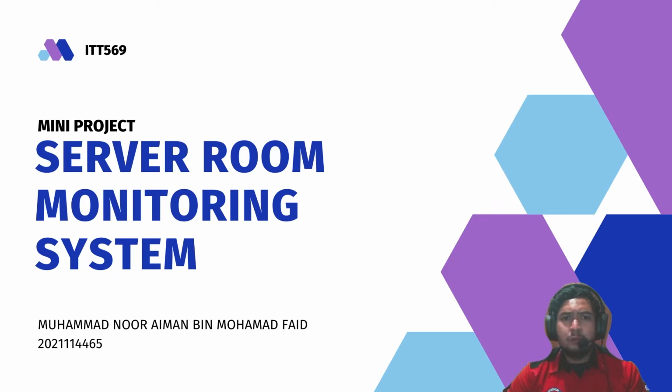For now, I will present my IoT mini project, which is a server room monitoring system. This system will record and send the temperature, humidity, flammable gas, and fire detection to the Blynk server so that it can be displayed on the Blynk mobile application. This monitoring system will also alert the user if any value is lower or beyond the recommended value of the temperature and humidity. Any flammable gas and fire detection will also alert the user by the Blynk application notification.